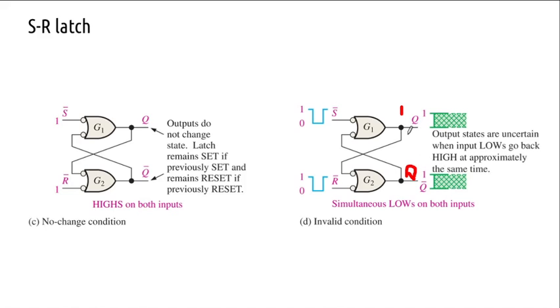So as usual in our way, here it was already 1, and suddenly it becomes 1 1, so the previous state, now 1 0, was retained. Suddenly we applied a 0, and when we apply 0, there is a race-around like thing. You say this 1 is fed back here, and this gate will try to go to high.